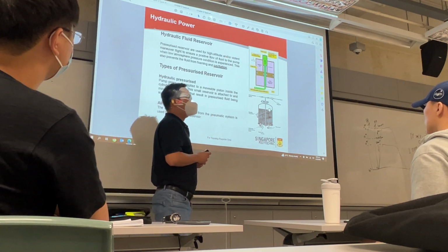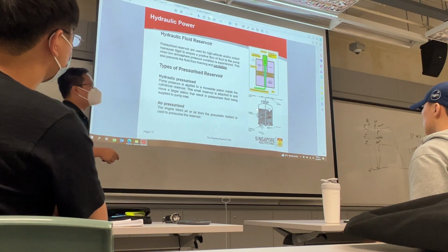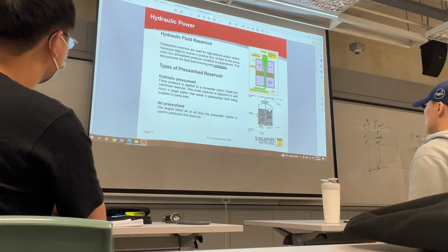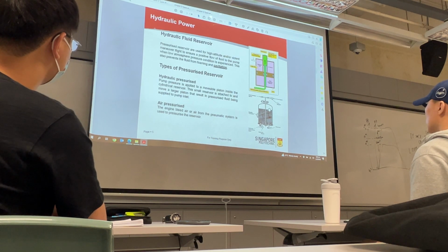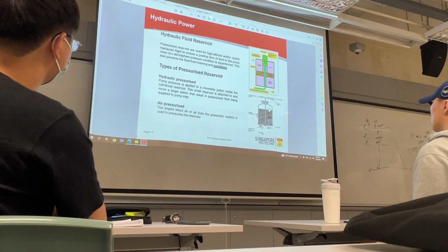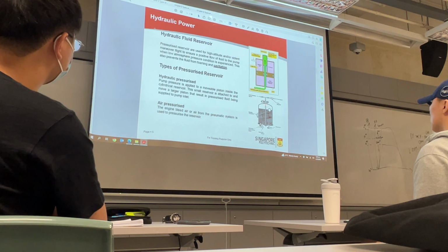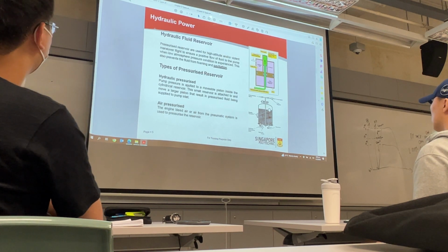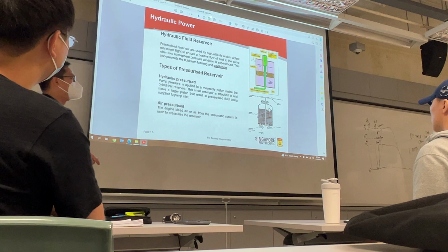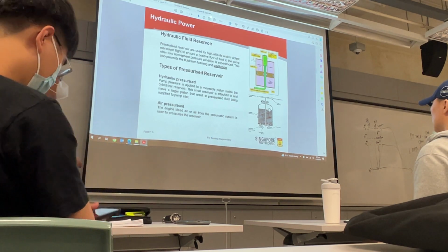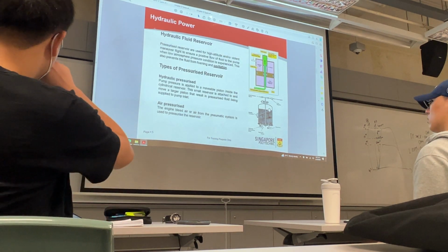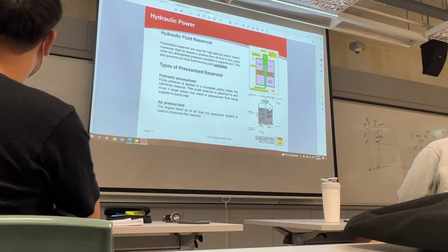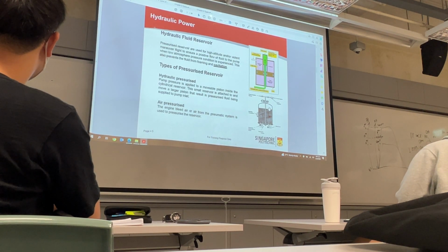One thing I want you to take away is this. Whenever you pressurize this system, when you want to remove any piping, do you depressurize? Yes. Must you depressurize? Because it's already pressurized after the flight, you have to. If you don't depressurize and you open it, fluid goes all over the body. I've seen a friend who, because of this air pressure, fainted afterwards. No joke.